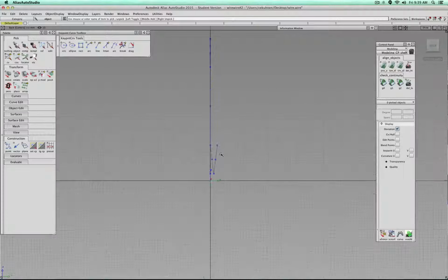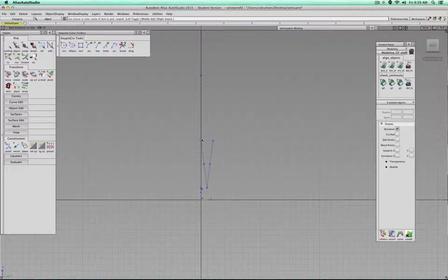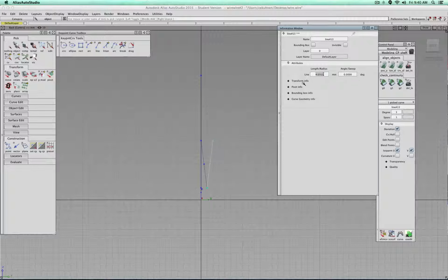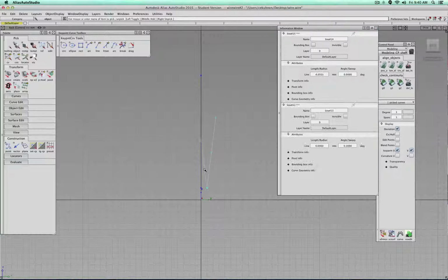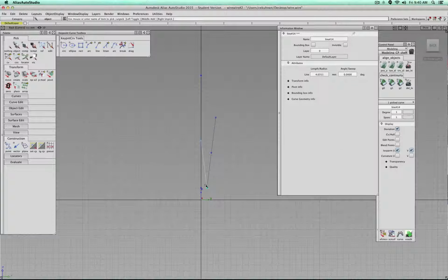But the problem is always when a surface ends right on another surface. Sometimes the software can have difficulties figuring out how those two surfaces intersect or where they intersect to cut. So best is actually to always make surfaces longer so they overshoot. So this means while this is now the height of 4mm, I might need this line to be longer. And the beauty of having drawn everything from the point is I can go now and simply say 6mm, and you see that it keeps actually the starting point and extends the line.